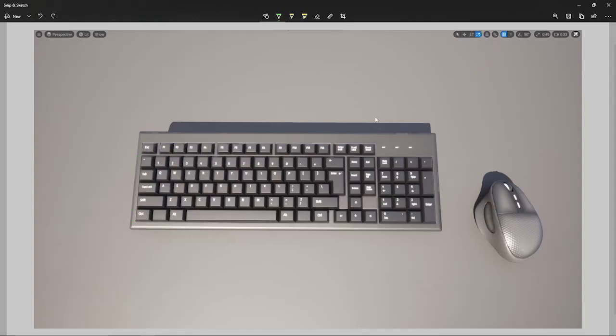You're going to hear me talk about this hotkey a lot because it is my favorite. It is the focus button. Any object you click on in the outliner or in the viewport, you can hit F and it will put that into the center frame of your viewport. Very handy for selecting objects off in the distance and then hitting F and flying right to them. End is another one of my favorite hotkeys, and it will drop an object to the floor.